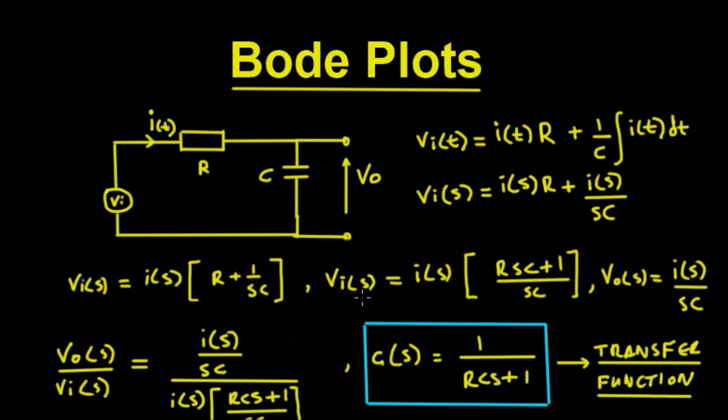So this is a low pass filter, but it's not an active filter, it's just a passive filter, meaning there's no gain stage involved in it. So we'll analyse this in terms of the time domain, and then we'll analyse it in terms of a complex frequency. In the time domain, we can see that the voltage here, V in, is a volt drop across the resistor plus a volt drop across that capacitor.